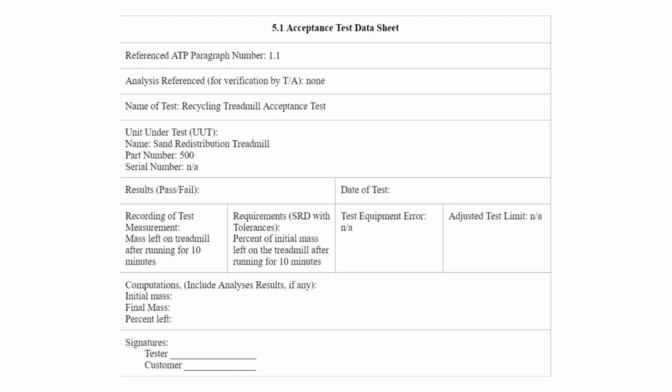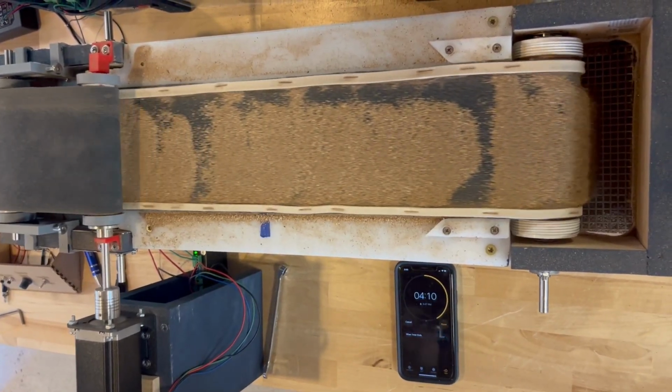Through the treadmill construction process, several improvements were made to the SRT subsystem. First, where the conveyor belt is inclined, the SRT had vibrations that caused the regolith to shift off the sides of the conveyor belt. To reduce the vibrations, a plastic sheet was added under the sloped part of the conveyor belt to stabilize the belt as it traveled up the slope. Rails were also added along the sides of the inclined conveyor belt to further reduce regolith loss. This was successful and did reduce the amount of regolith lost as it traveled up the inclined slope.